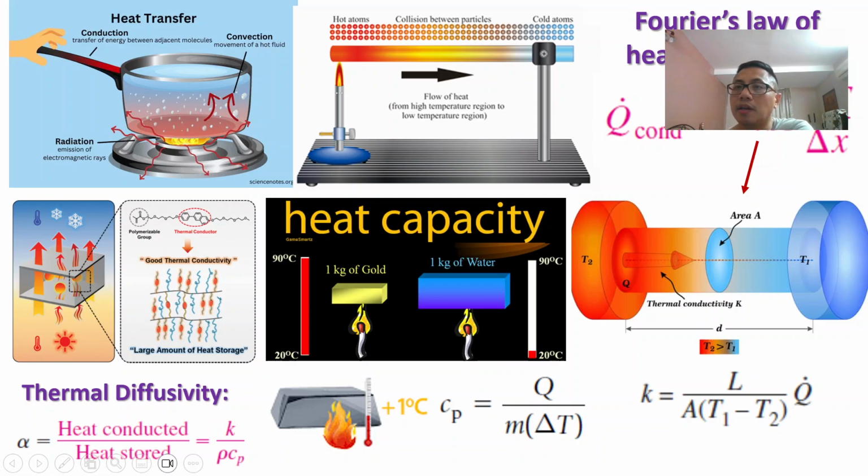The heat conduction can be described by Fourier's law using Q equals negative kA delta T over delta x. The k value here is a constant called the thermal conductivity. It can be measured if you have a setup that can measure the length and temperature difference between two sides with a known amount of heat supplied to the metal or any conductive material.